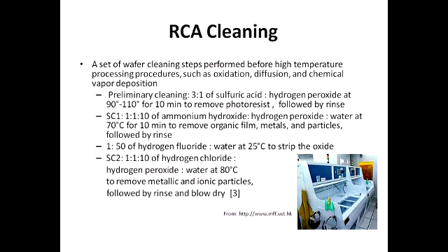SC1 is to remove organic contaminants using ammonium hydroxide. After SC1, usually oxide is formed, so hydrogen fluoride is used to remove the oxide.